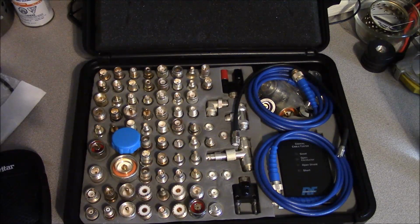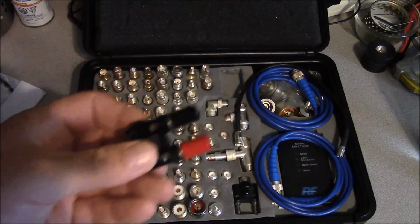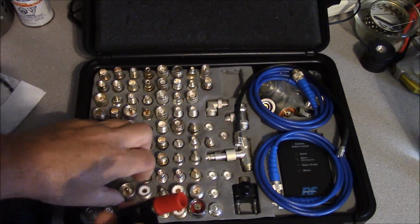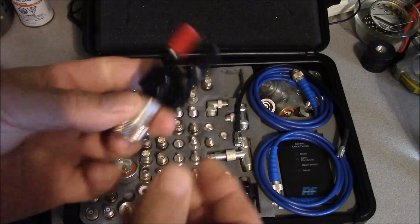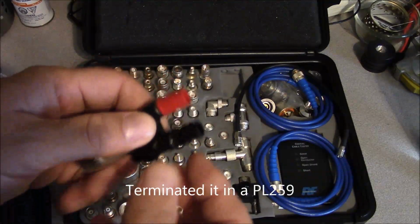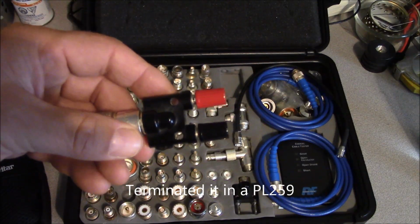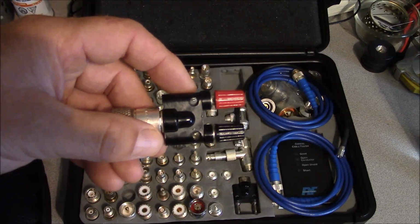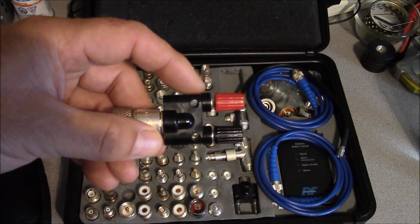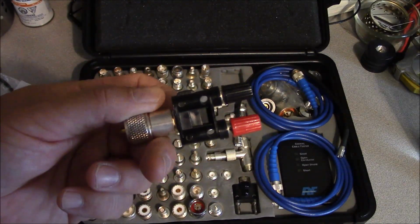Now, when we move from coaxial cable to our contingency and emergency feed lines, we're going to end up needing something such as this right here, which is merely a binding post adapter to an RF connector. And as you can see here, we've now terminated it for a PL259. But one of these right here is useful because you can take a balanced feed line arrangement and connect it to the back of a piece of radio equipment, or you could just go ahead and put a vertical radiator and a counterpoise, making an effective back of set antenna if required to do so.